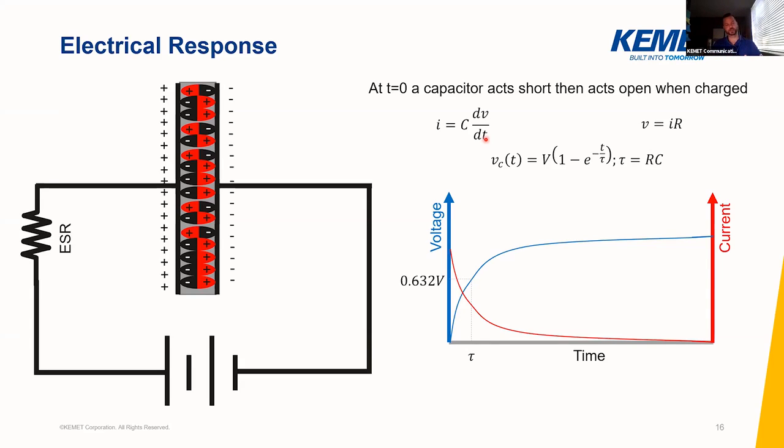You have a set of electrode plates coming from one of the termination sides of an MLCC, and then you have the opposite electrode plates coming from the other side of the MLCC, and they form this sort of interdigitated, interleaved pattern from one another, and that's where these parallel plates come up.